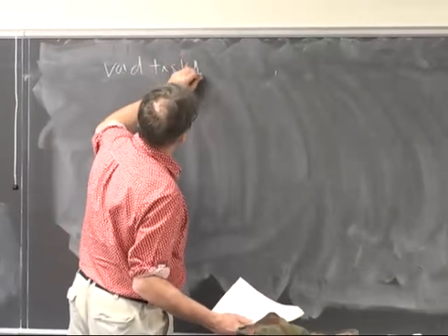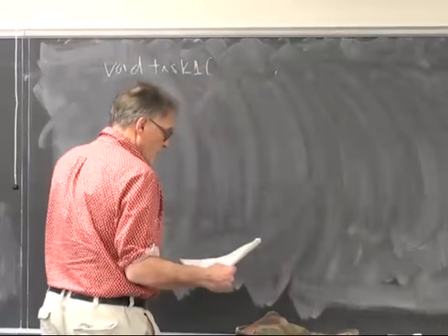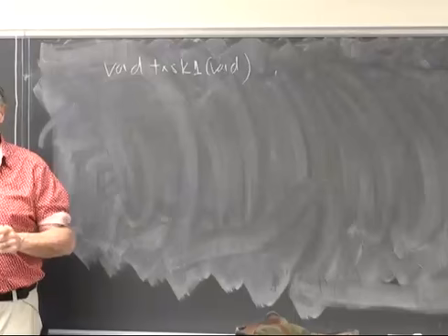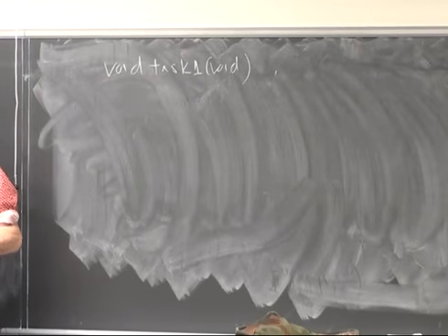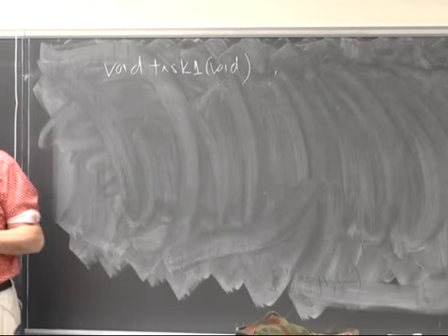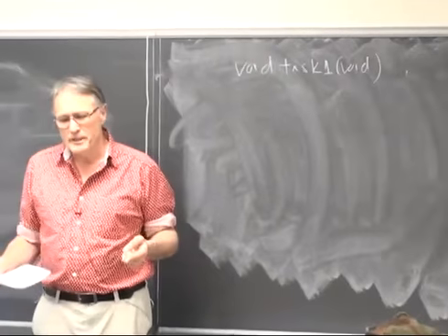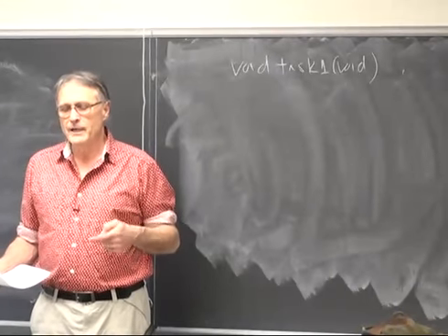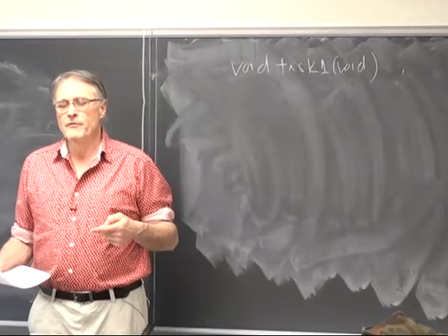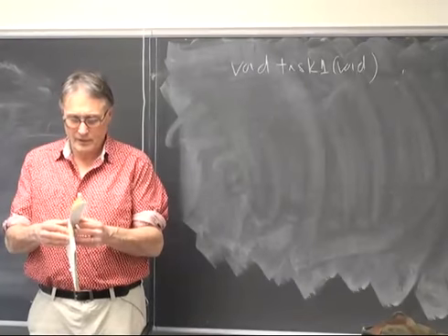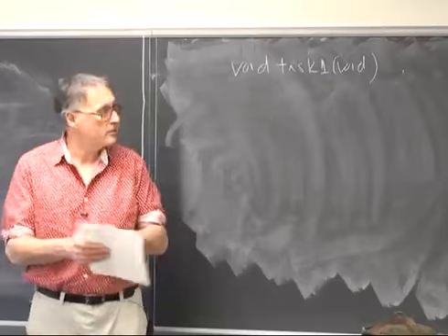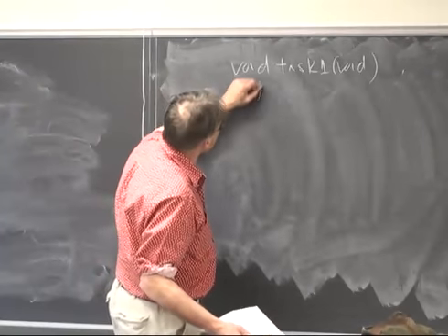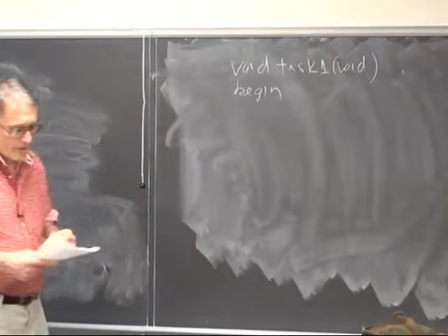And if you will recall from last time, task 1 is going to blink a light at either 2 per second or 8 per second. And main, which is acting as kind of the world's stupidest scheduler, is scheduling task 1 by reloading a timer with the value of 250 milliseconds, I think. Yes, 250 milliseconds. And as usual, we'll use begin rather than curly bracket.